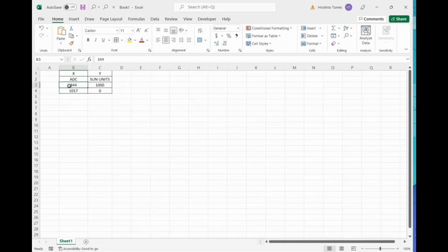Like for example, when it was very sunny, we get a value of 344. That 344 is going to be converted to our special unit of 1,000 sun, whatever that means. And when it's dark, pitch black, then we get this value of 1017, and that means 0 sun. So this could be ADC. The ADC could be anything, and this part is the important part. This is where you recover the unit back. This could be, for example, degree centigrade, degree Fahrenheit, degree Rankine, and so forth. So this is the part that is important to pay attention to.